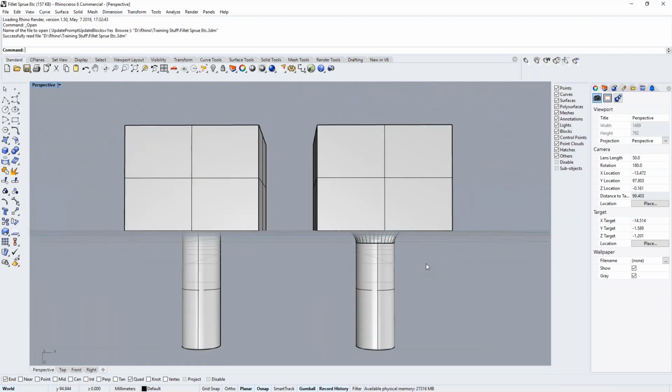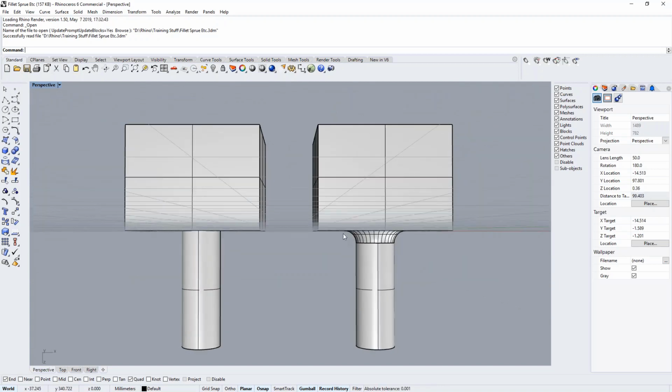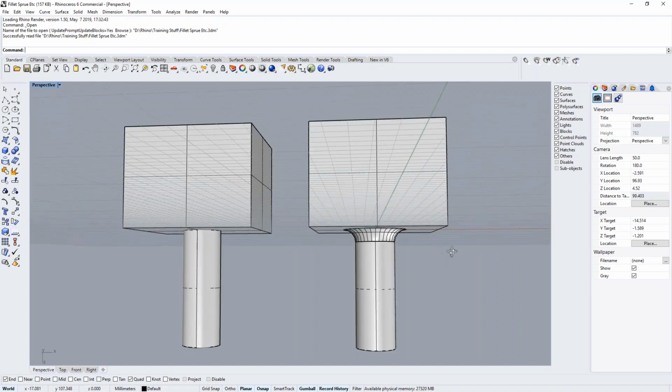You've got to think about fluid dynamics and turbulence in the casting process, and not leaving really sharp edges at surface junctures. One thing I'm glad I remembered to mention just now is that a lot of people are probably using resin printers, whether it's SLA or DLP type printers. They create a photopolymer resin model. And that is very popular in the industry right now.